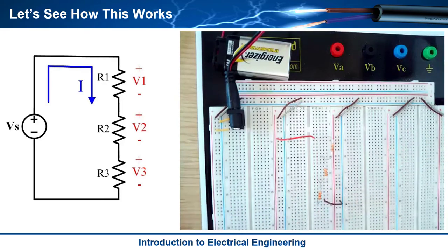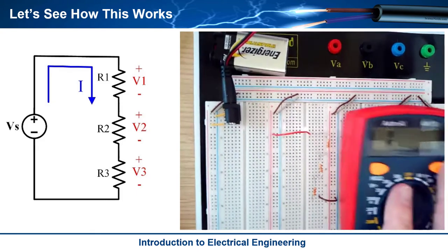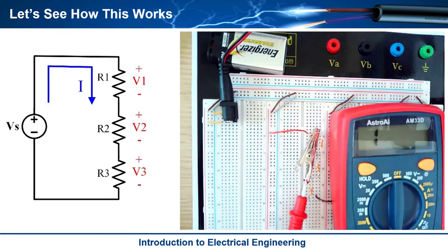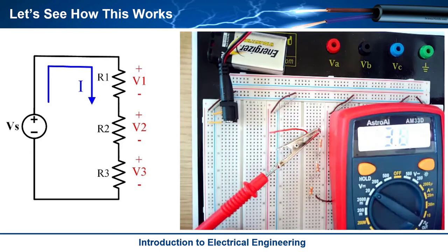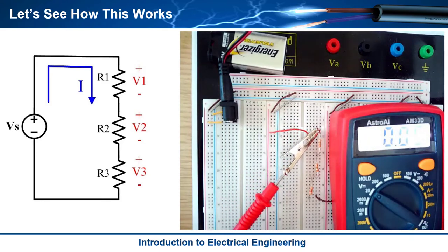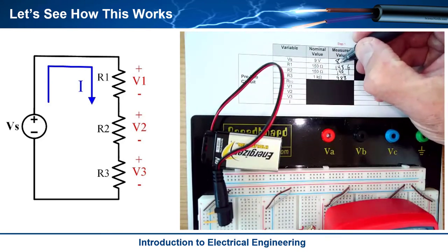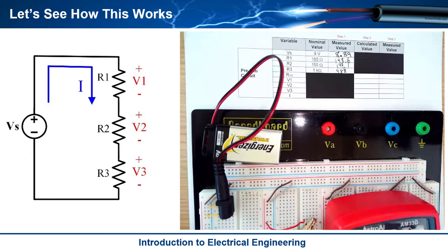Okay, so now that this thing is active, and so there's current flowing. So now what I want to do is I want to come back in and measure the voltage across the entire thing. So I can go ahead and tie in on the top right there, and let me make sure I'm in voltage before I do anything. So up to there, backlight, I don't know if that helps. Okay, and what do I get? I get 8.89, okay? So 8.89. So now I come down here and I got 8.89. So now those are the values that I can actually use when I do calculations.